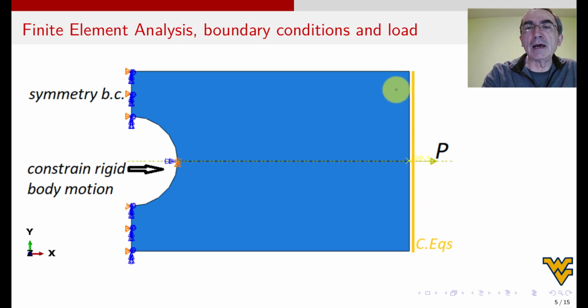And then I'm going to get a nice uniform stress here, which corresponds to the one that I calculate with the nominal area. So load divided by nominal area will give me the stress in this region over here. And over here in this region, I'm going to get load divided by net area. And then at these points over here, I'm going to get the maximum stress, from which I can calculate the stress concentration factor.